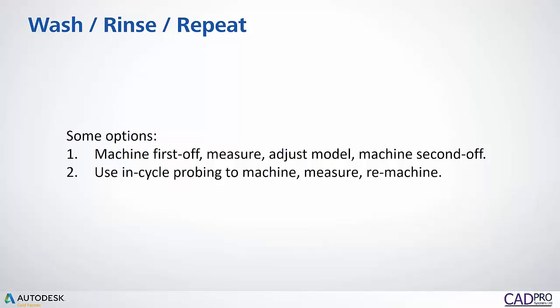I think it's a good thing to point out, because there's a lot of times where people are toolpathing directly off the model, and it's a common practice for CAD designers to just dimension to nominal. So even though a bore might have a +5, -0 tolerance, your toolpath from the very beginning doesn't take that tolerance into account, and you actually machine your part. So I'm glad you showed this and how you can put the model at the center of tolerance so that when you're machining the part, you have that full tolerance to work with. It's a good thing to be aware of as people do more and more machining directly on the model, thinking about how that geometry is defined.